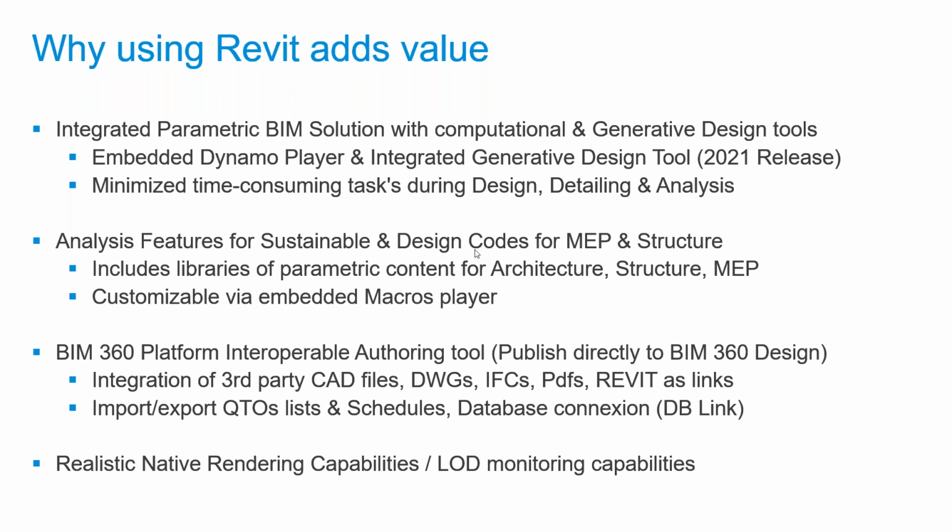The closest you would get would be the BIM 360 platform with the coordination model itself, being able to view that in a browser. But I think it's important to mention that the export to AutoCAD command is the way you would get pure AutoCAD solids out of Plant 3D that would be able to be linked into Revit. And then Revit has the DWG export capability.